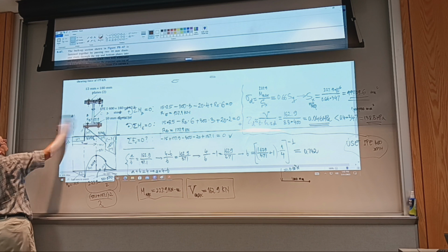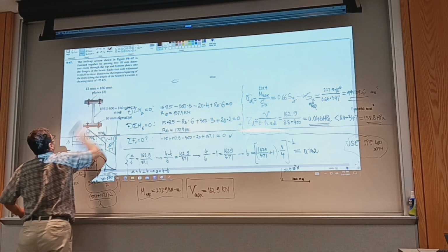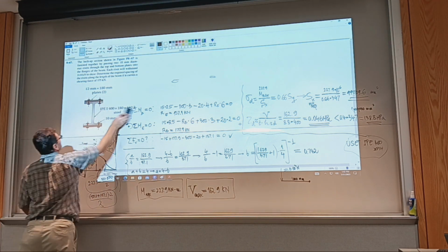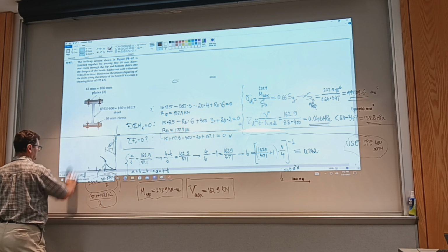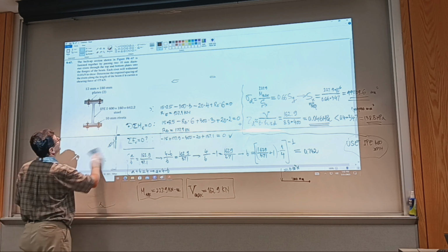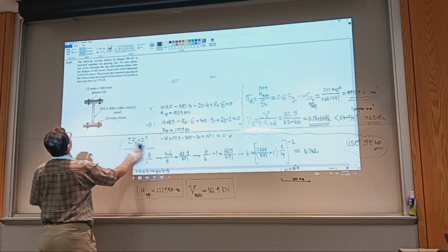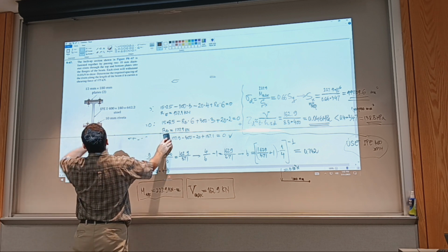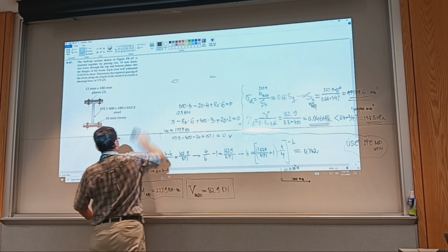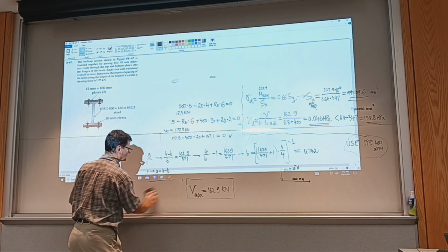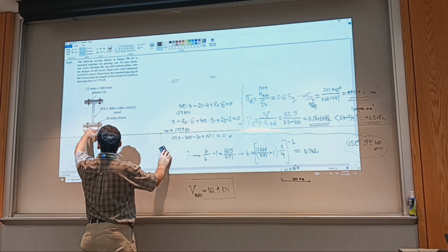So this is about shear flow, sizing the fasteners in an I-beam that is reinforced with some plates, and we use rivets, and we are given the allowable shear force for a rivet, and we want to know at what spacings they should be. There are two.